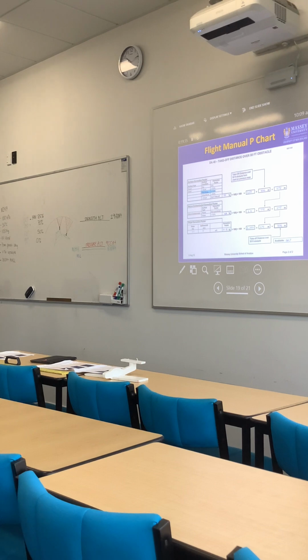What do we need to do? Could we offload a passenger? That would probably be the easiest thing to do. Maybe they have to get the bus. So make sure you go through those steps, because it's critical, all right? If you don't do the whole comparison with the distance available and required, and then the personal minima stuff, that's where accidents happen.